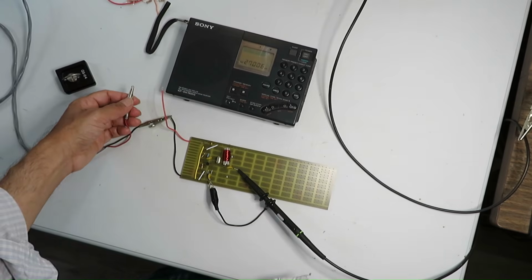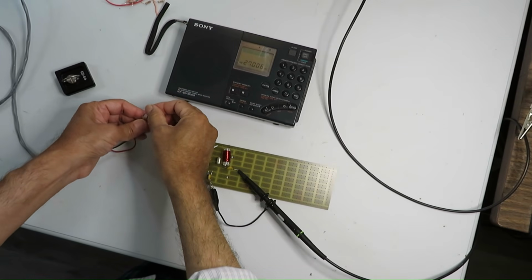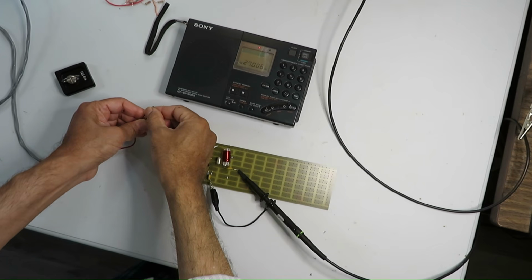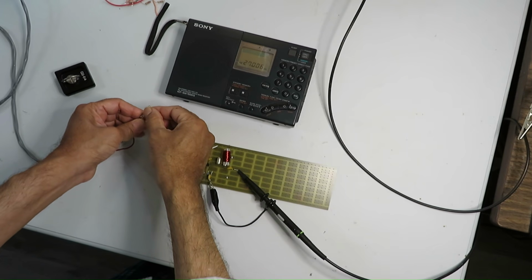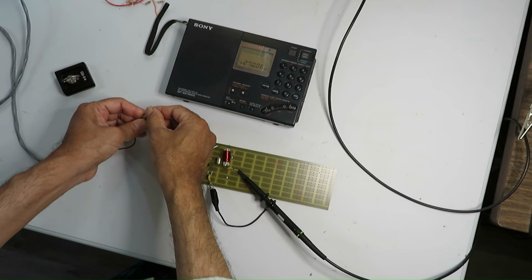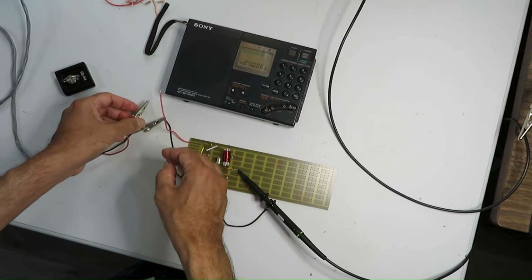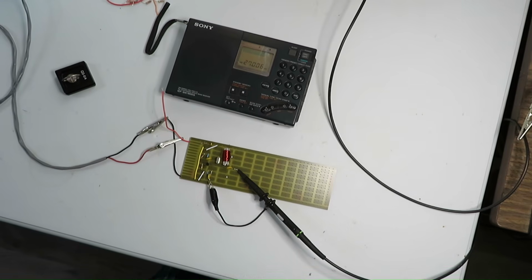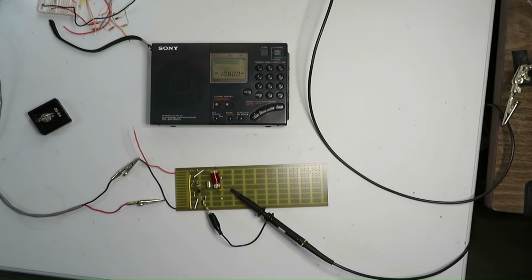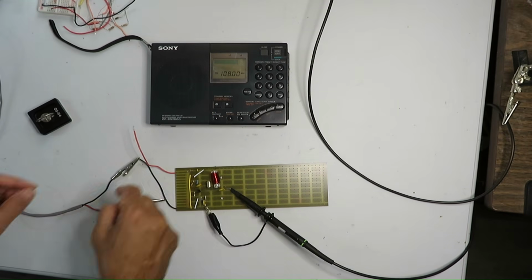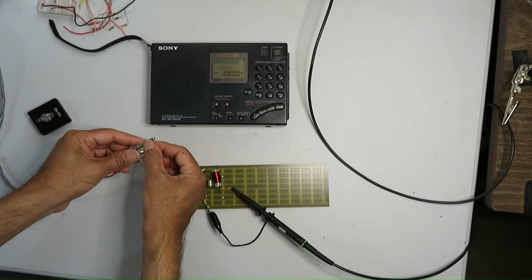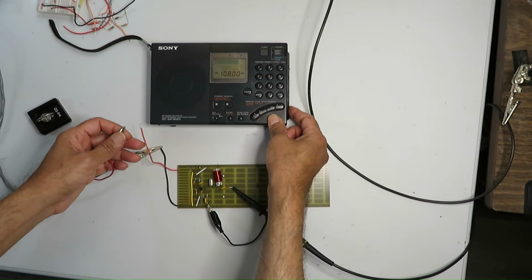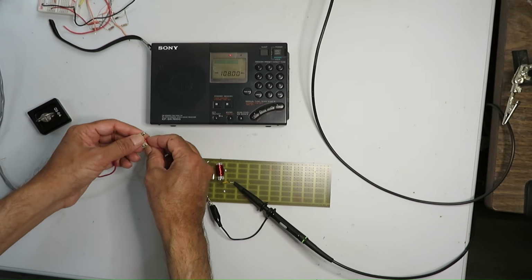So you can detect the RF using an HF radio. I am tuning the radio at 27 megahertz, and you can hear the sound at the oscillating frequency. Now you can also use an FM radio. You can see that it is tuned at 108 megahertz, and you can easily detect the oscillation by hearing the sound.